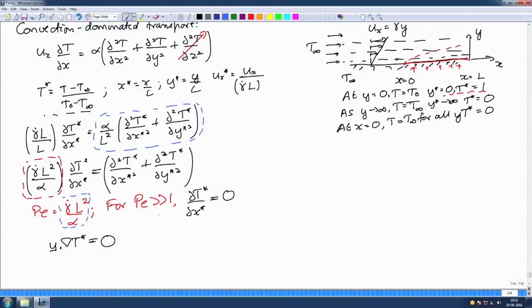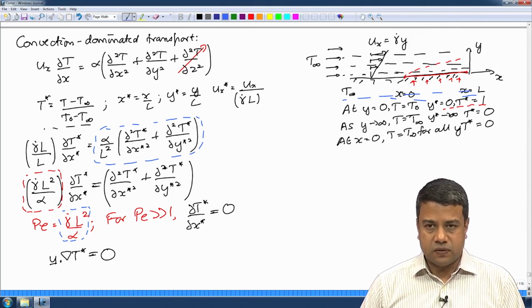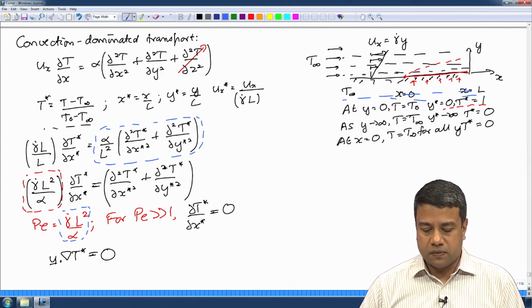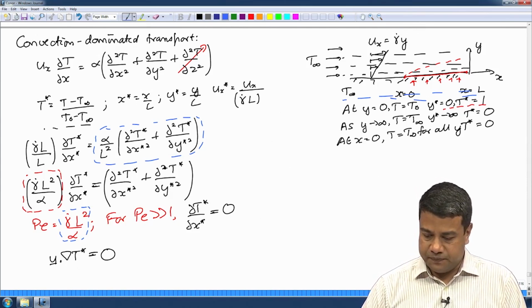If you write the convection diffusion equation, for example, for the simplest case of heat transfer from a heated surface, where the velocity is only in the streamwise x direction, the surface is at the same temperature as the fluid for x less than 0, and the section for x greater than 0 is heated up to a higher temperature. You want to find the flux of heat and get a Nusselt number correlation for the temperature field.